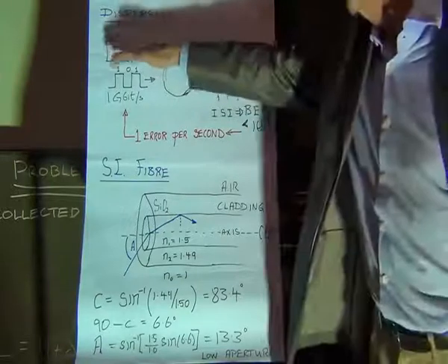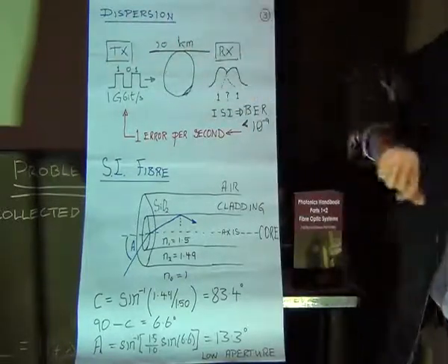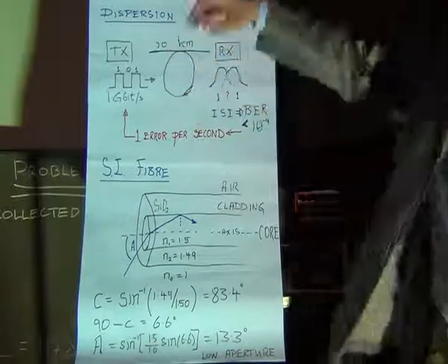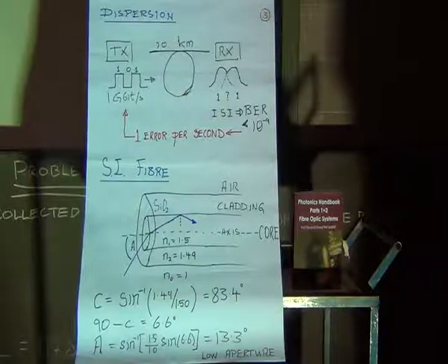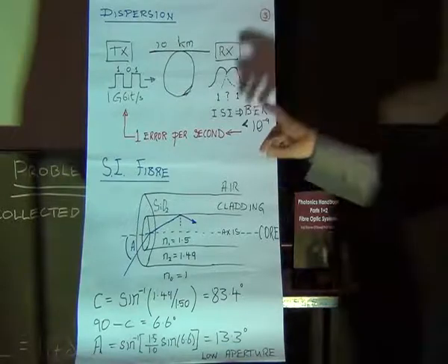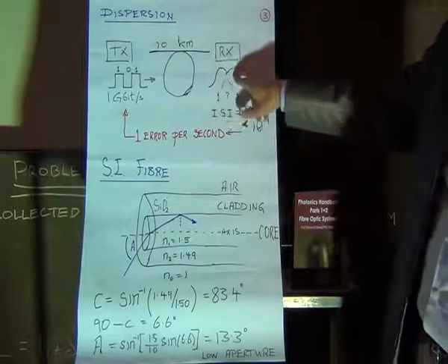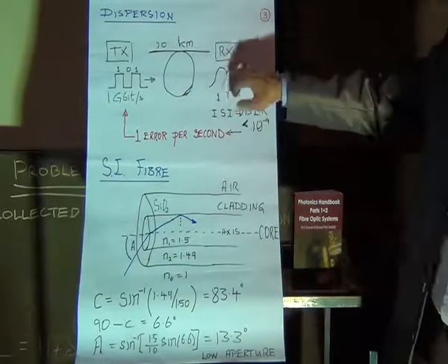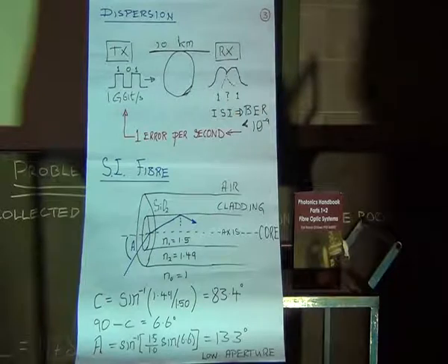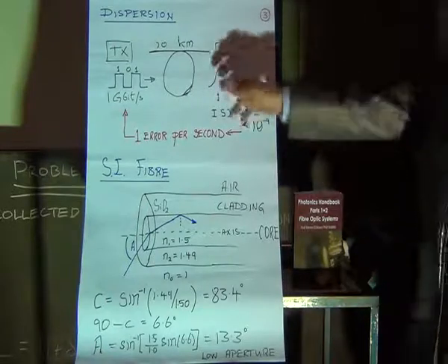Meanwhile, the height of the pulses is also reducing because we still have a small amount of impurities and a small amount of scattering in the fibre, so that losses occur. Okay, if this process is taking place, we call this inter-symbol interference. The ones and the noughts and the ones are interfering with one another in our decision circuit.